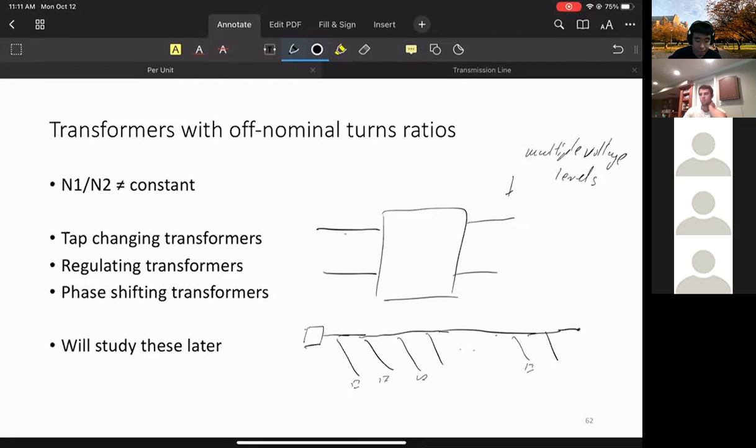So what happens is, let's say you start off with a 1 per unit voltage. By the time you get to the end, this voltage tends to not be 1 per unit anymore. Okay, so if you have a circuit and you have things in the middle that draw power, what does the voltage do to get to the end? So you have a long circuit, you keep adding load in the middle. Then what happens to the voltage? Anybody have experience with this?